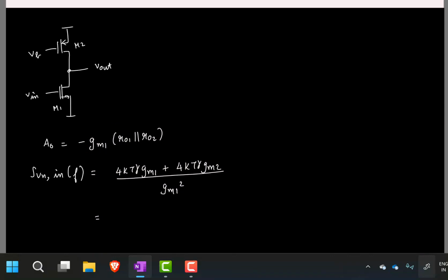So can you suggest some change that I can make here so that this transistor is not merely doing this, but is also actively participating in signal amplification? No, not gas. Just here, two transistors, simple common source. If I have a PMOS current source here, that is reducing the output resistance and also adding to noise, right? What I'm asking is, can we make a minor change here so that this transistor also actively participates in signal amplification?